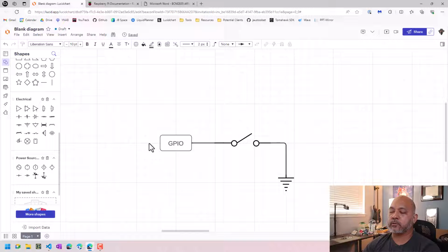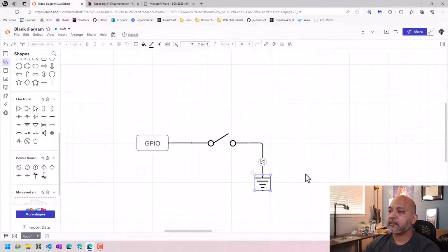We connect a switch to the GPIO line, we connect the other side of the switch to ground, and maybe you decide to put a resistor in place somewhere or not. But the problem we have here is that yes, while the switch is closed, when it's open, we don't really know what the voltage here would be because there's no input voltage when the switch is open. In electrical terms, this pin signal is floating.